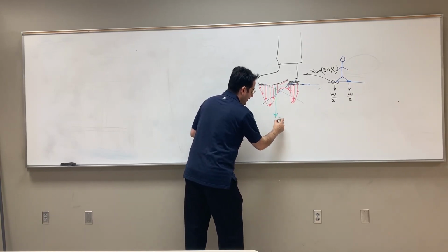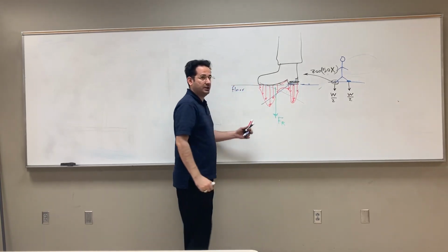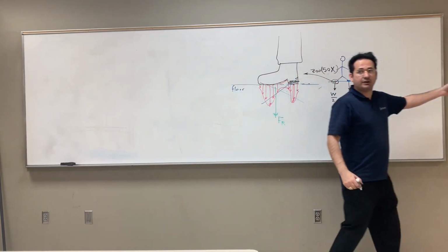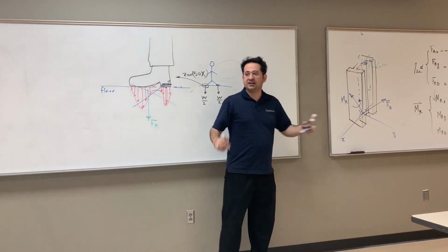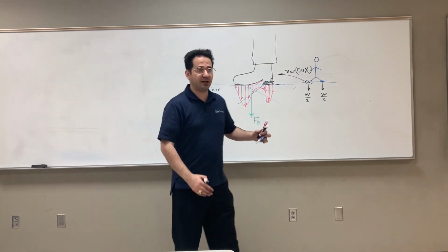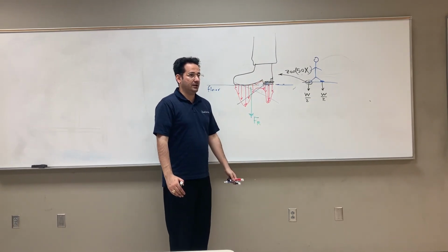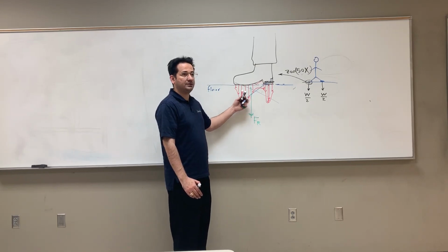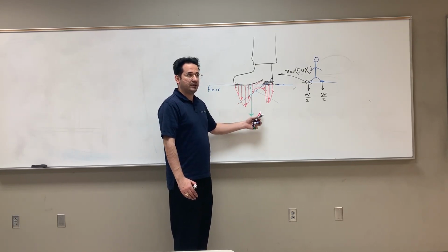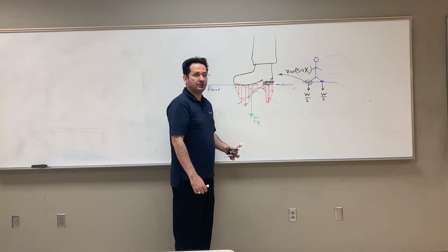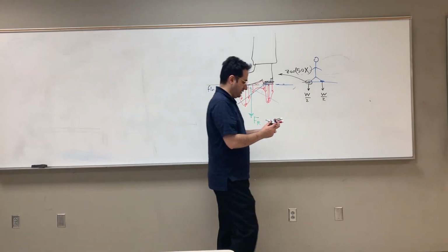Because if I have just one single load instead of a distributed load, I can do all the analysis I've done so far. I can reuse all the technology I have developed so far, and I can analyze the system, right? So that's what we're going to talk about today: how to replace a distributed load with a single load and just eliminate the distributed load. So here is the procedure.